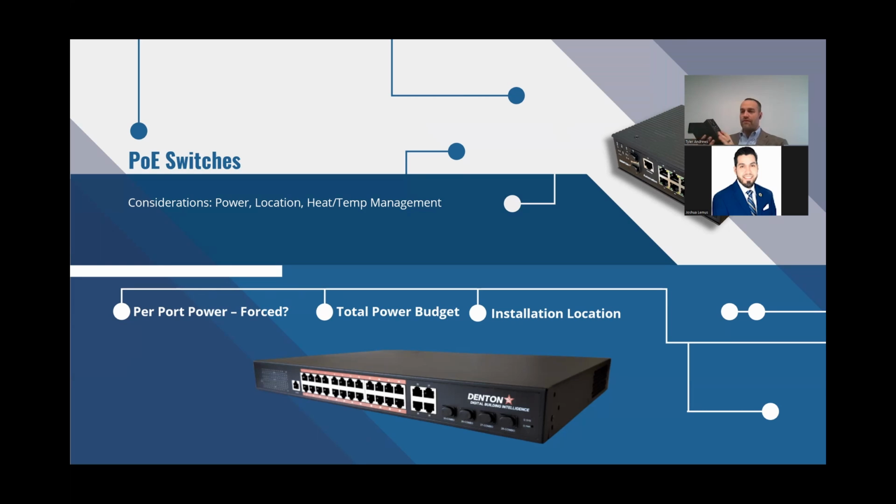An important feature about PoE lighting is you need to make sure you go with an 802.3 BT, ideally type 4 PoE switch. What a type 4 PoE switch does is it gives you a power budget of 72 watts at the port at minimum. That's kind of the industry standard. If you don't get 72 watts out of that port, you're not actually using an industry standard switch.